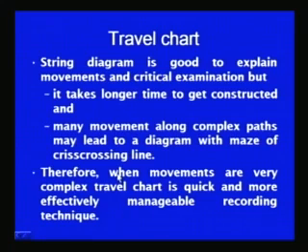Therefore, for movements which are very complex in nature and large in number, the travel chart can be effectively used to study the kind of movements taking place of the worker or the material between the different stations. This travel chart is found very quick and effective in recording the different movements of the worker and the material between the different stations in the course of production.